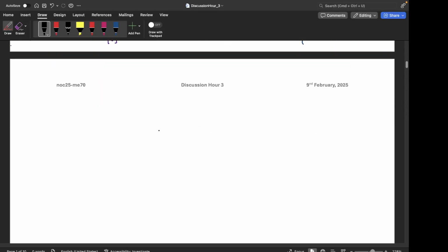If you remember, the transformation matrix from the nth frame to the n minus 1 frame is written as R n to n minus 1, then the position in the n minus 1th frame, and then 0 0 0 and 1, right? This is a 3 cross 1 vector, this is a 3 cross 3 matrix.